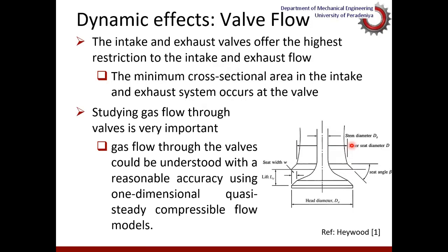So therefore, it is very important for us to seriously look at the flow through valves. And with one-dimensional models, we can model them with reasonable accuracy, assuming it's a quasi-steady compressible flow, just to get an idea about what exactly happens in these processes, thermodynamically and in terms of fluid mechanics.